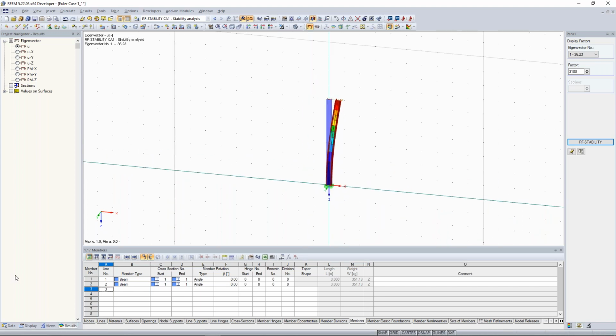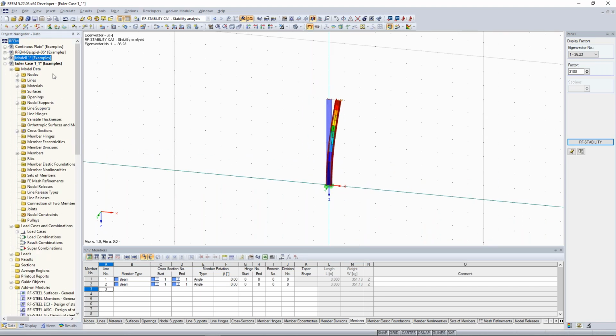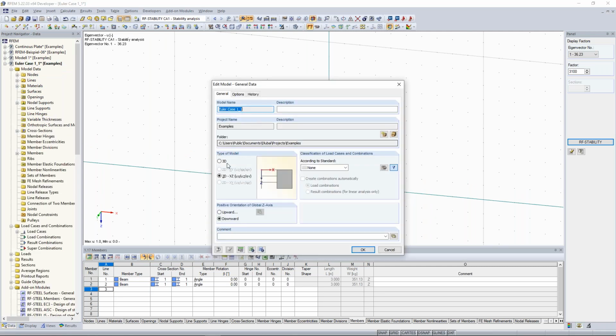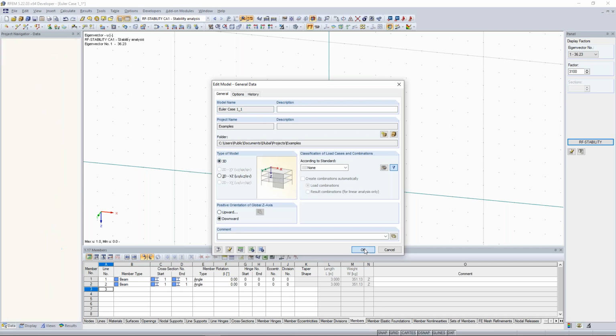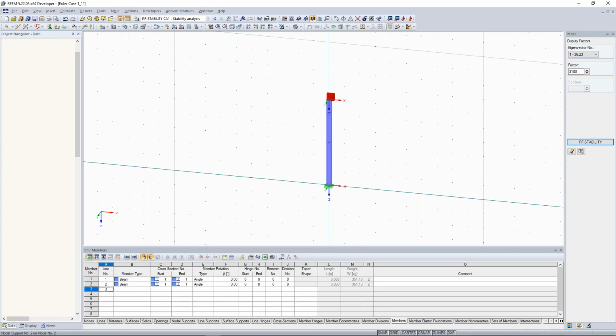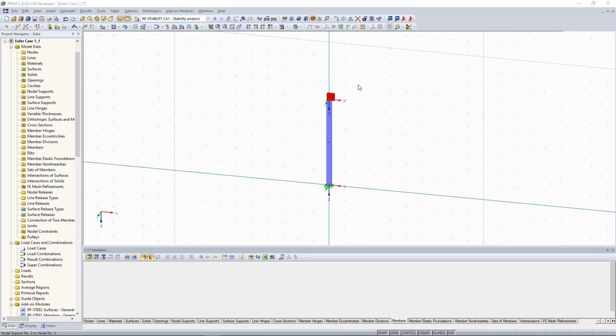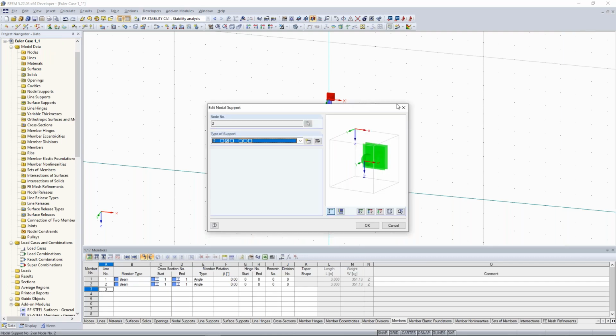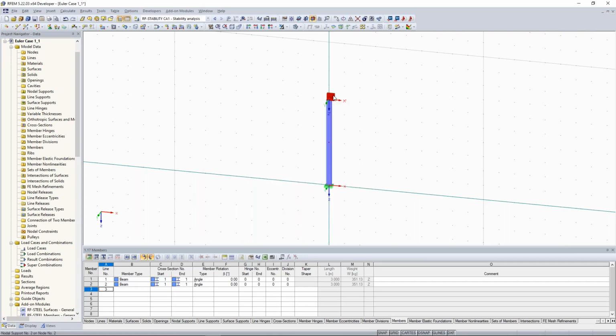So what happens if we do more? First of all, I'm referring again to the type of model to a 3D. I delete this support direction there. Delete also this node by the help of delete node, but merge joint lines members together and make this 10 meters high.